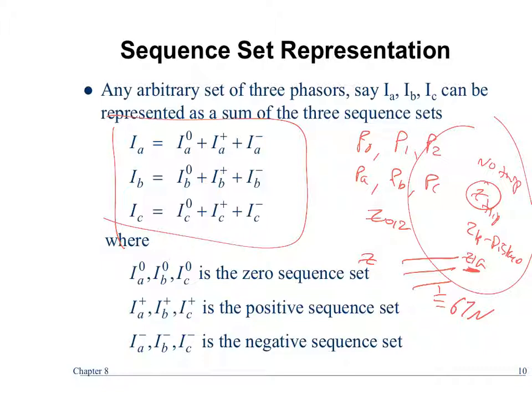So, one of the things you do is you actually look at faults, and you actually have a ground that actually has a wider path. So remember how I said it's a circle? In ground, many times, I've actually seen it as a rectangle, because the ground impedance can be so high that you can get some wonky results. We'll talk about, if you're interested, distance elements and all these shapes. One's a circle and one's a rectangle. They're actually called a mho characteristic, and the other one's called a quadrilateral characteristic. But we'll talk about that if you take the following class.